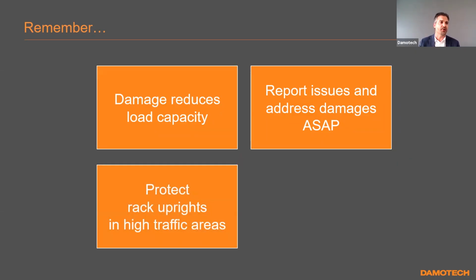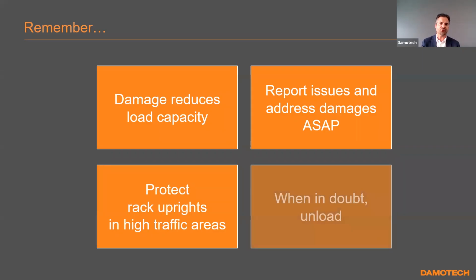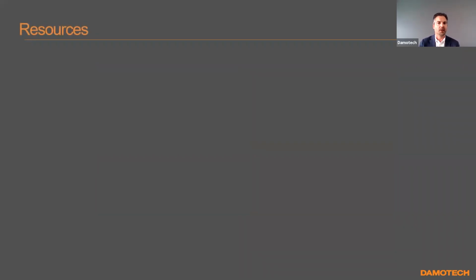We didn't talk too much about this, but in the event that you see a high risk of potential damage, even though there hasn't been damage yet, if you see an opportunity to better protect your racking, for example in a high traffic area, be proactive and put those measures in place. And the most important point to remember in today's discussion is, if you see something and you have doubt, you're not sure or it's unclear, don't take any chances, unload the rack, and everyone stays safe that way.